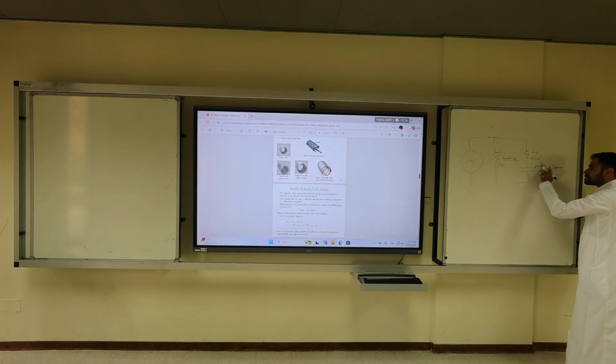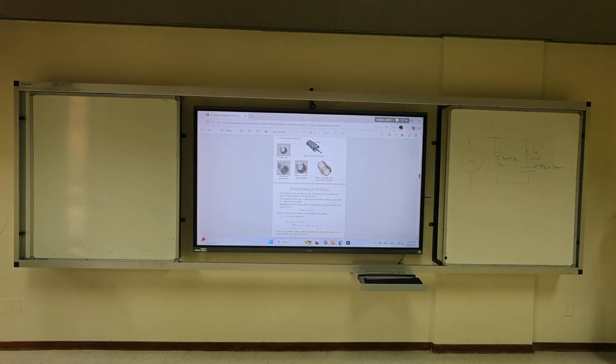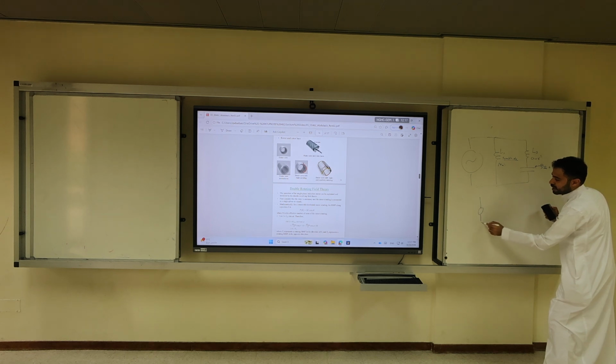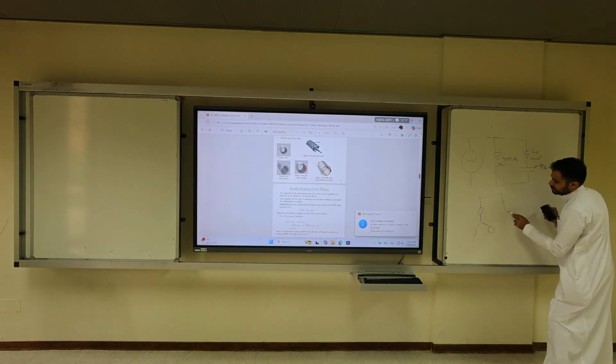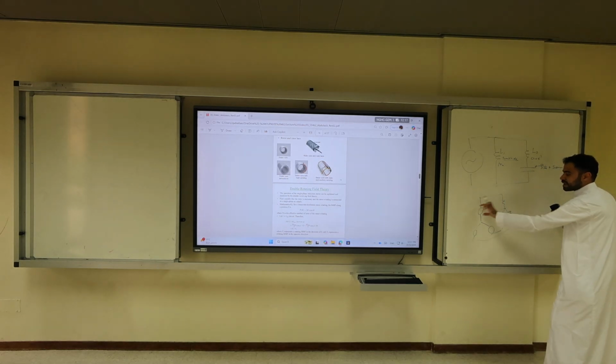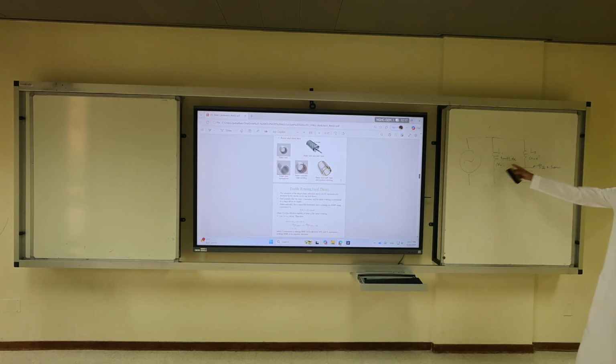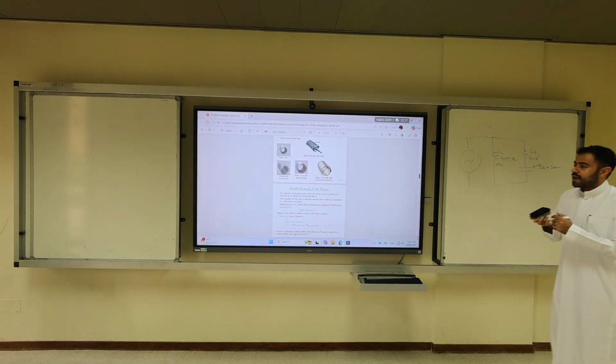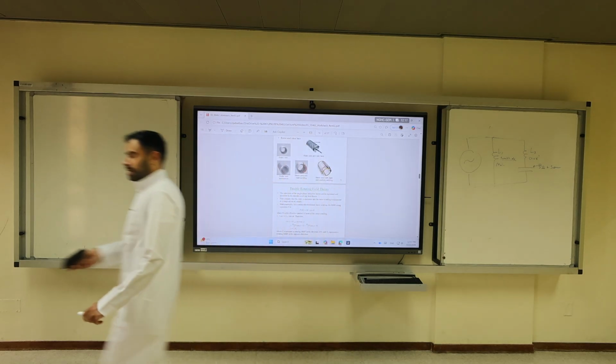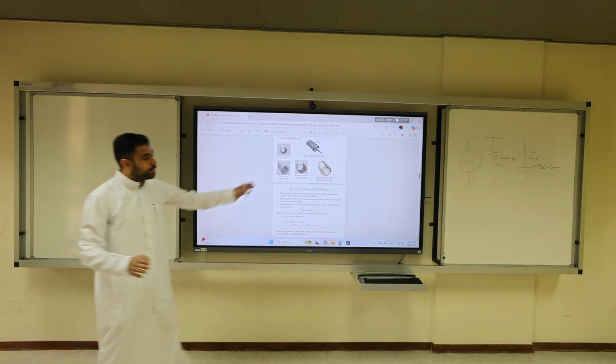but the flux comes from 2 different phase shifts. Get it? Yes. Get it why we call it fake 2-phase? In the 3-phase induction machine, you remember you connect phase A here, phase B here, phase C here. So everyone gets a phase by itself. This is not the case. I only have one phase, but I play with the connections and the values of the windings to get different phase shifts. And that's why we call it auxiliary. Get it? This is very important to understand.